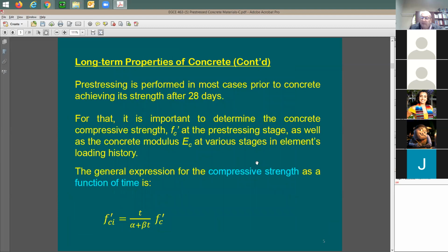All right. Now we have this issue about the initial pre-stress and then the final pre-stress. The tricky part is you apply this high pre-stress force based on 189 ksi in each strand, and you apply it on concrete that's not at 100% of the full strength at 28 days.